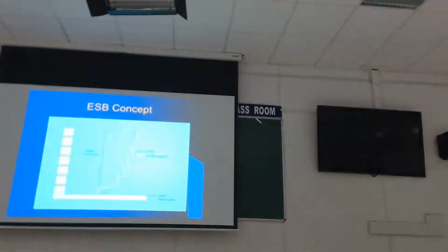We can work out how the soil is going to oscillate in its first mode and draw the shape. So the black line is what we expect the soil to do for a given earthquake. And the rubber deforms, but the aluminum doesn't. So you can match the black line in a stepwise fashion. If you do that, the amount of reflections you get from the sides will be minimized. They won't be zero, but they'll be significantly minimized.